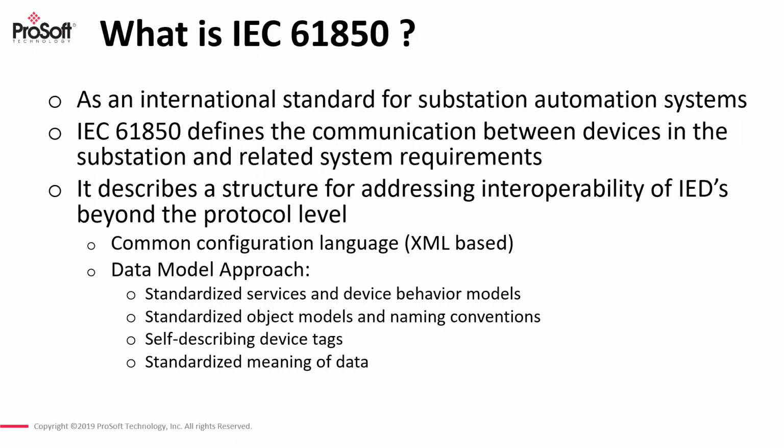A lot of this came from the fact that Modbus, DNP, and even the IEC 60870 protocols all started out as serial protocols. They either operated on RS-232 or 485, so networks with very low bandwidth. IEC 61850 started out and has only operated on an Ethernet network.